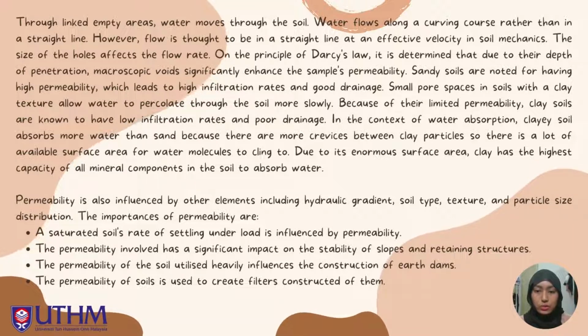The importance of permeability: a saturated soil's rate of settling under load is influenced by permeability. The permeability involved has a significant impact on the stability of slopes and retaining structures. The permeability of the soil utilized heavily influences the construction of earth dams. And lastly, the permeability of soils is used to design filters constructed on them.